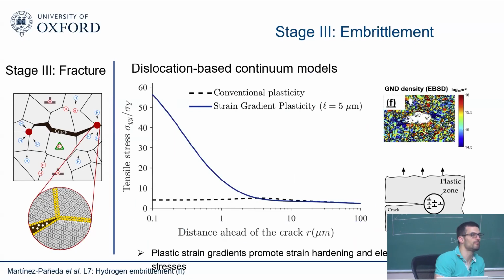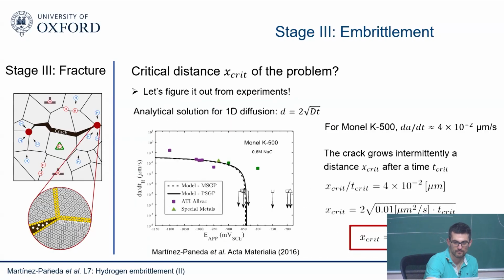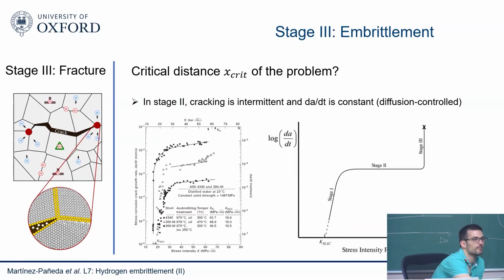The slide you were showing, the crack in the 3 stages. Yes. The first curve is typically for a stress corrosion cracking type of phenomenon, right? Is this for hydrogen embrittlement as well? Sustained load cracking, are you talking about that? Or rising load experiments as well. You get some sort of subcritical crack growth, in a constant load type of test or an increasing load type of test as well.